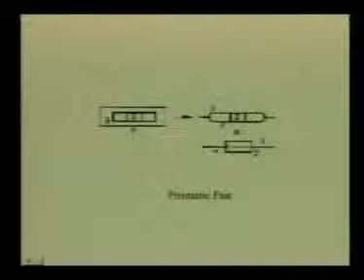Prismatic pair, say between body number 2 and body number 3. The block, which is the body 2, has relative translation along this slot. In the kinematic diagram, we may show this prismatic pair between body 2 and 3 by this line diagram, or sometimes, to make it completely unambiguous, we represent it like this. There is a prismatic pair between body 2 and body 3.